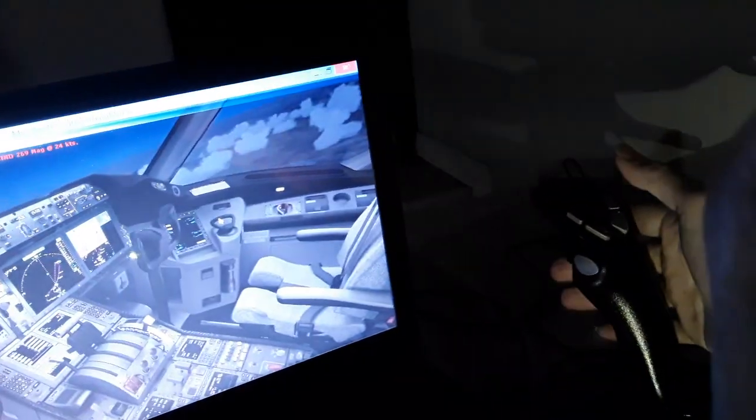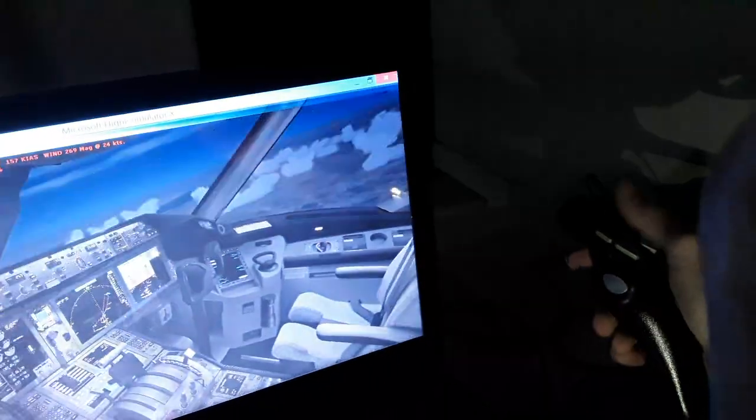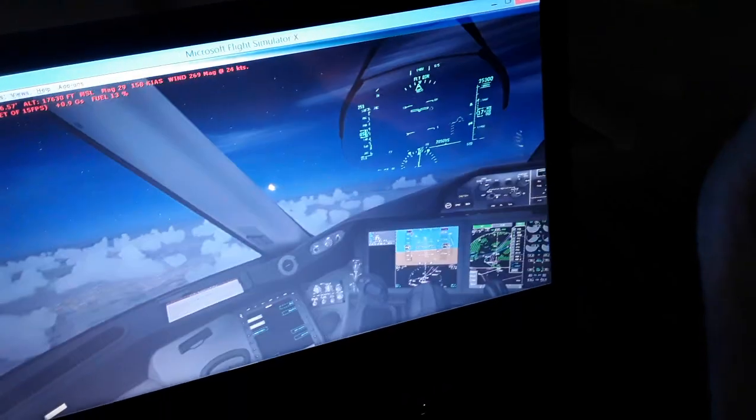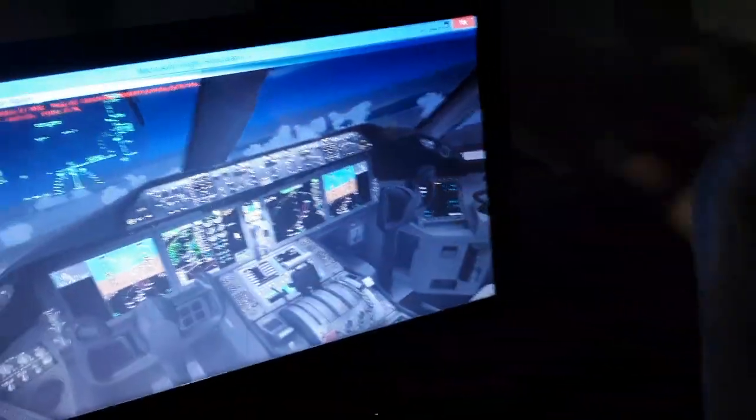We can leave the hands off from the aircraft, no problem, for as much time as we need. Only need to make small inputs from time to time, as you can see. Only the airplane can do that, stay level with the hands off from the yoke if it is trimmed well and has the right thrust and flap settings.